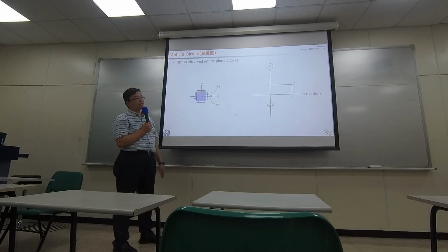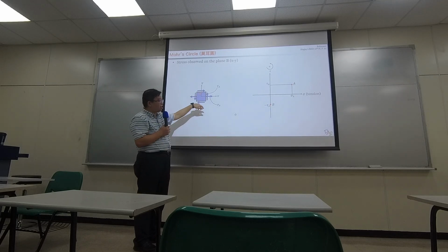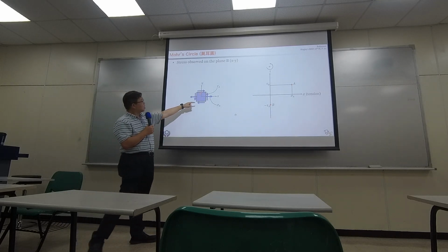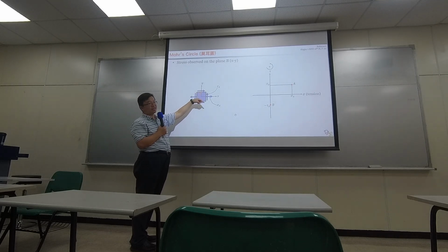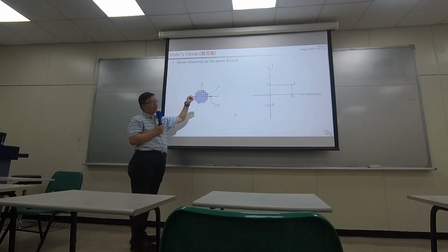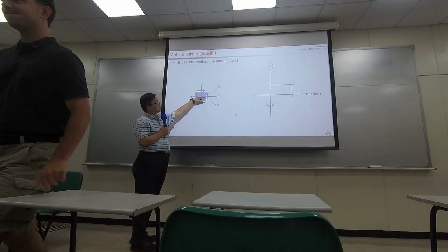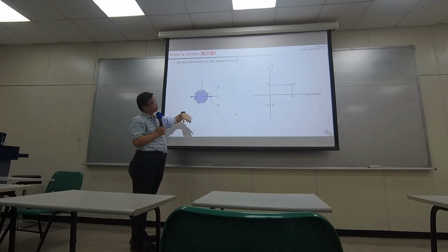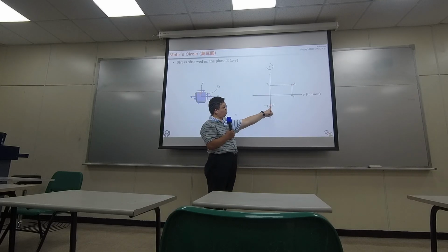Over here it's important that you made a 90-degree change on the element. It's like you walk around the element and make a turn, changing the direction of your investigation. The direction of your investigation was rotated by 90 degrees in the real world. And over here you see there is a clockwise shearing stress, so in the way I keep a record of the stresses, this is a negative value, but the same magnitude. The only difference is that it's changing its direction. So the shearing stress would be negative tau A.